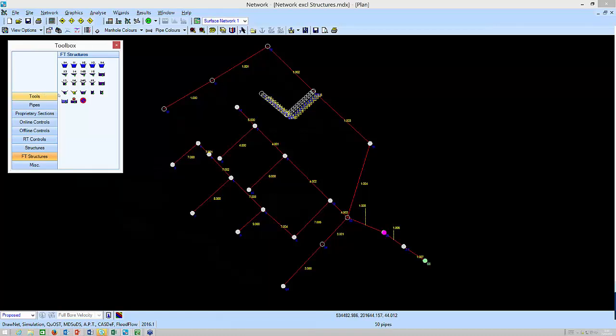when you're designing, by the way, just a word to the wise, when you're designing your network with draw nets in MicroDrainage, having worked in MDSuDS, had an idea that I'd be putting in these swales and what have you. So I'd put swales in automatically within the model and then put in the flow through structure swale onto the swale location. It kind of works better because you've put the swale in at the surface within the model in MicroDrainage. It'll marry up nicer. Not a drama if you don't, but you'll be prompted for levels and things like that.